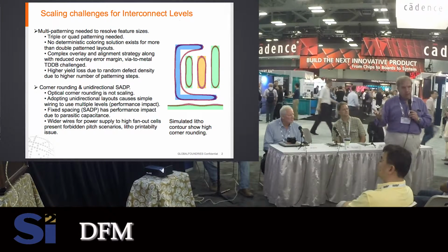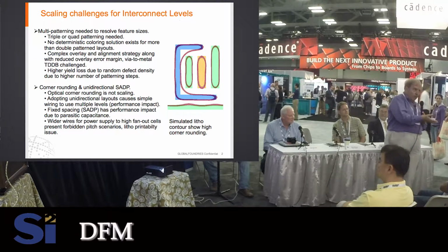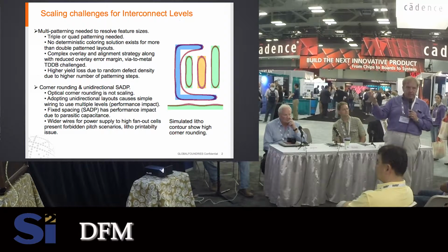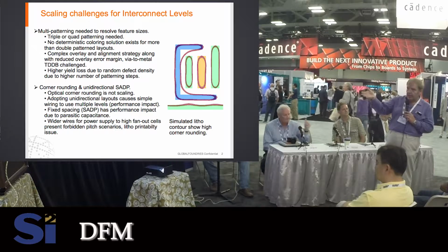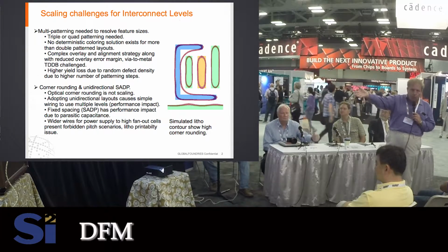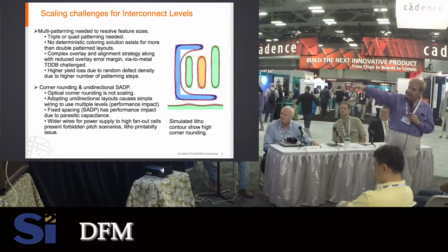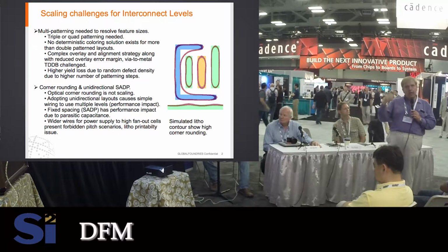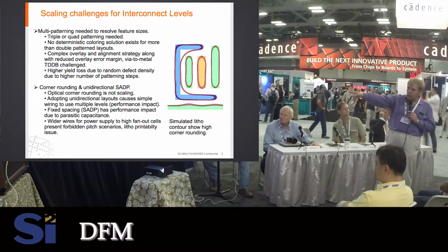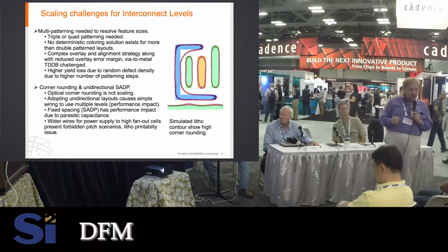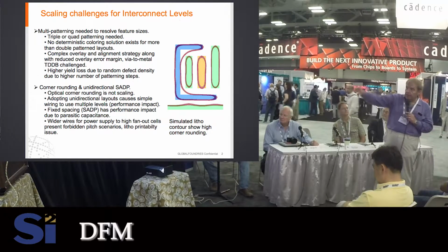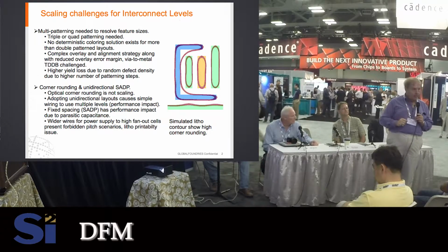So you're trading off area versus performance, acres of silicon versus fortnights of time. Additional issues here are wide wires. All these wires inside your design are all min wires. Your rails, like the green at the bottom, might be a 3x or a 5x wire. You have litho problems that you're going to need to deal with there.